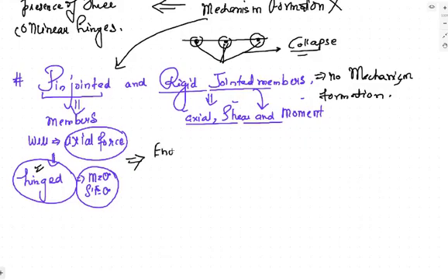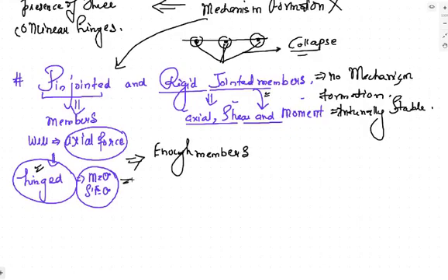So in that case, with respect to this pin jointed case, in their arrangement there should be enough number of members. एक तो enough members होने चाहिए. जनरली ये तो इंटरनली स्टेबल ही होते हैं आपके पास, ये स्टेबल जनरली होते ही होते हैं. पर इनके साथ प्रॉब्लम क्या होती है? These rigid frames are internally generally stable, क्योंकि रिजिड होते हैं, मूवमेंट होता ही नहीं है इनमें एक दूसरे के रिस्पेक्ट में. सारी फोर्सेस तो ये लोग न्यूट्रलाइज कर देते हैं. But these pin jointed are internally unstable, so because of this there should be enough members present and also the arrangement should be adequate.